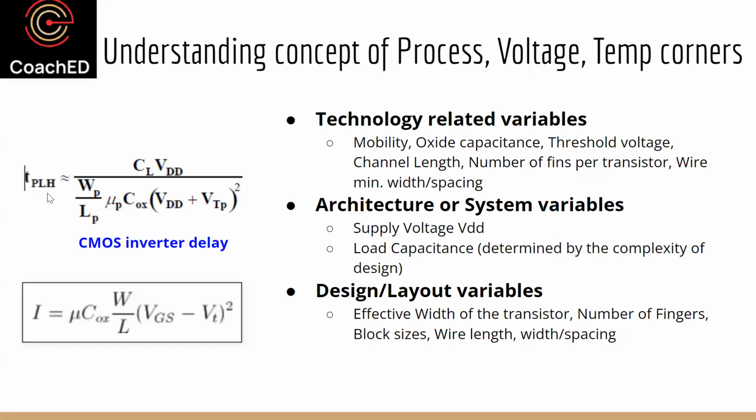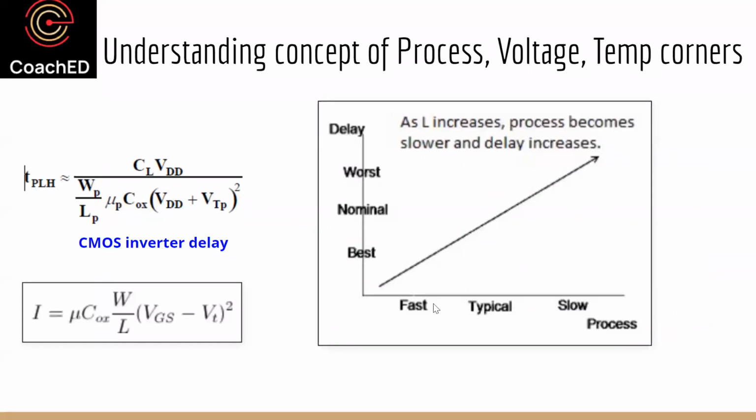And then when the transistors and the circuits are meeting the spec, it's called a typical corner, typical process corner. So when people are saying fast, typical, and slow in this specific picture, this is what it means, as I described. Due to process variation, some natural variability, you are having some gates becoming fast, some of them becoming slow, some of them meeting the spec.